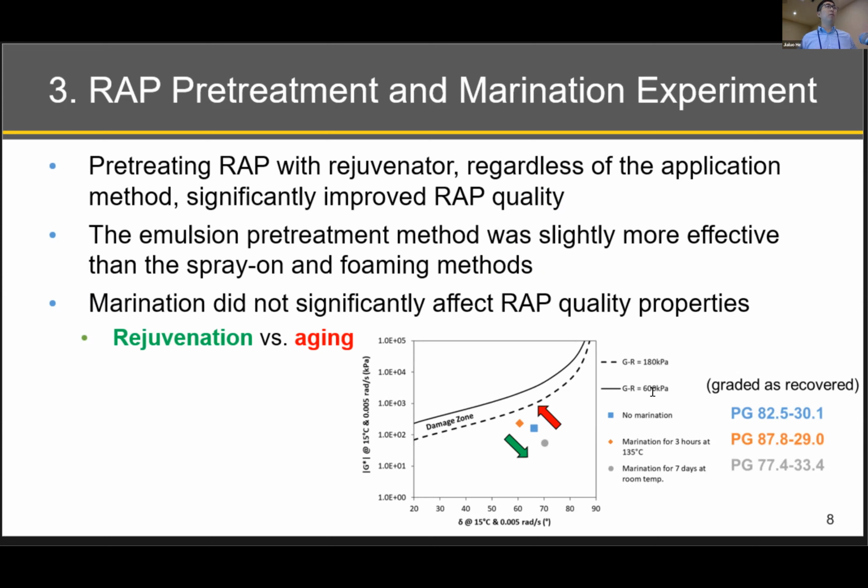As I mentioned before, higher temperature is going to accelerate the diffusion. That is something we want. But at the same time, high temperature could cause further aging of the asphalt binder. If you use low temperature, the diffusion may take a long time. If you use high temperature, diffusion will be faster, but aging could have a detrimental impact. So this is something we'll look into in the future, to try to balance out these 2 fighting mechanisms, if you will.